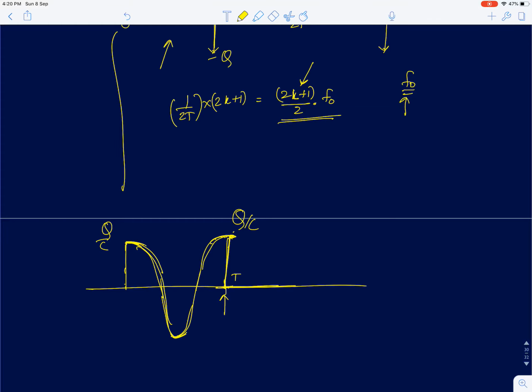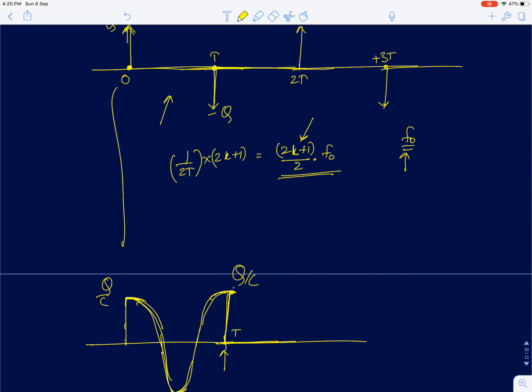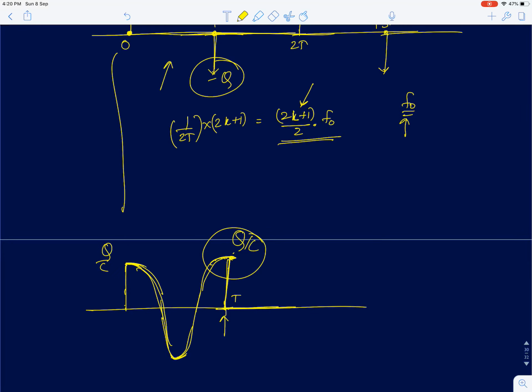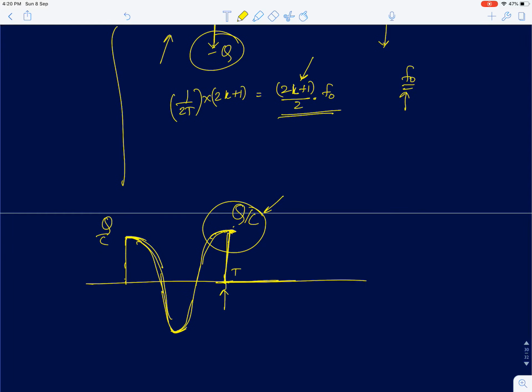Now what happened here is that the current source was negative here. The current source is transferring a negative charge, but the voltage across the tank is positive. Therefore the power will be dissipated by the current source. Where is this energy? There was an energy which was stored across the capacitor. All that energy is lost instantly, and it is lost across the current source. The current source dissipates this energy and brings it to 0.